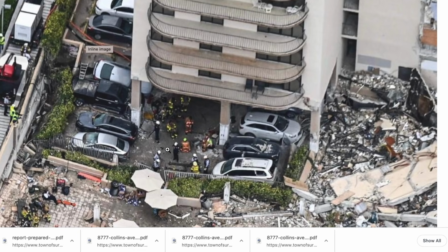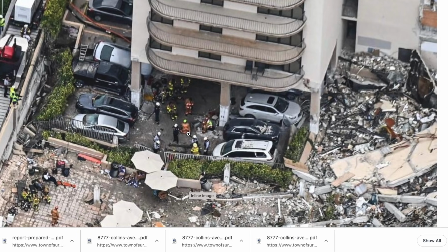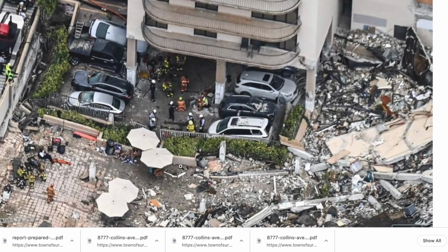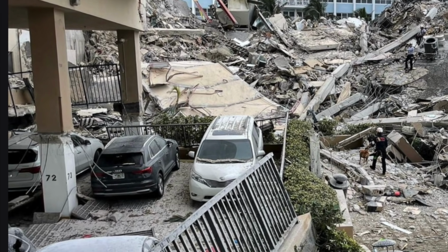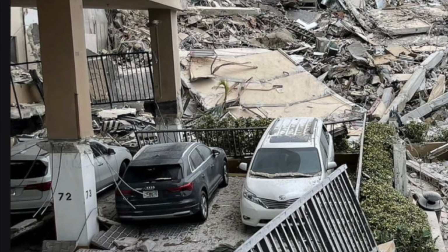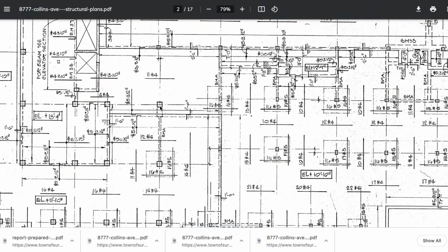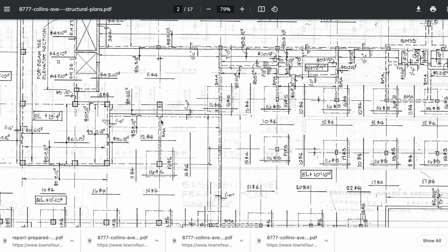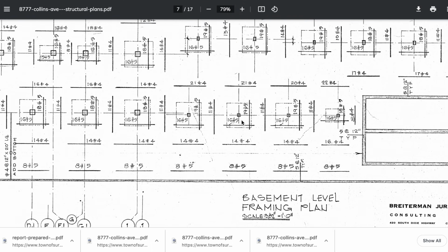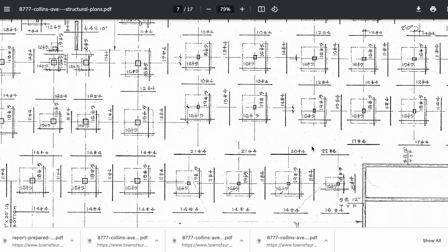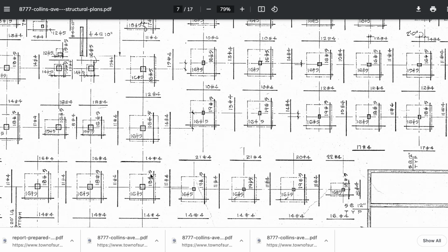So that return, if you look right to the right of the building, will be a return of concrete similar to where the gate is. And then you turn and put concrete there along with gate fencing. I'll show you in the next image. Column. So that's supporting the outer wall, and they wanted to put a beam further out here. There's your column. There's that rebar that's not present. It's the railing detail that, let's see, 1, 2. All I gotta do is find the larger ones in line.